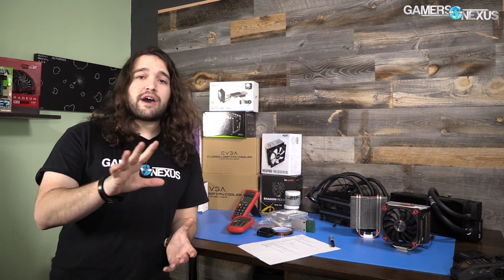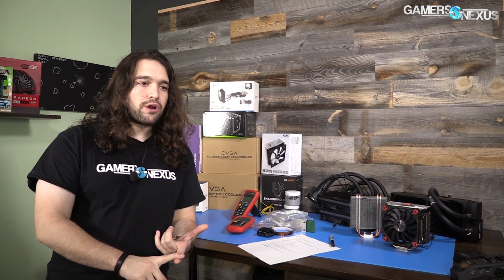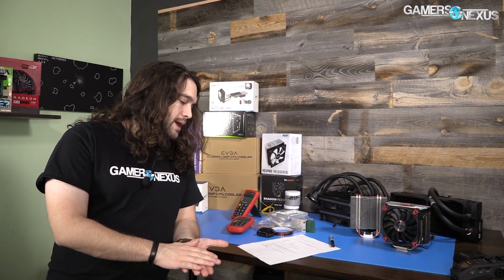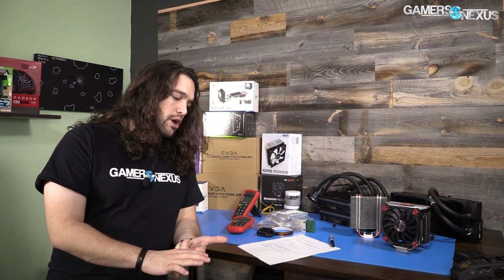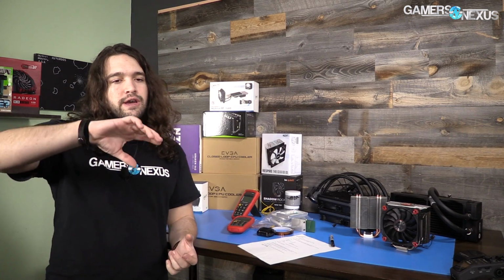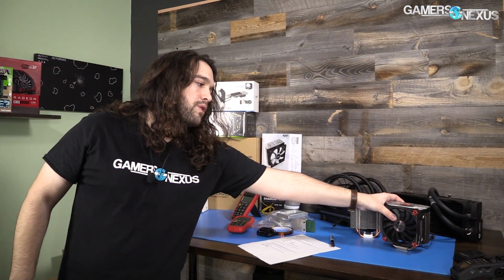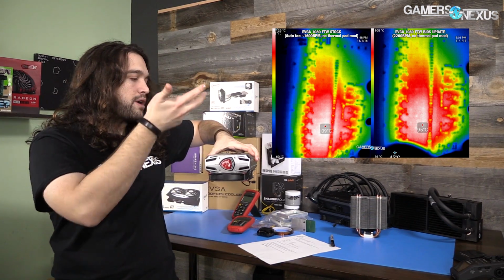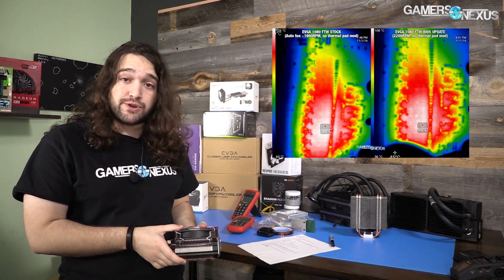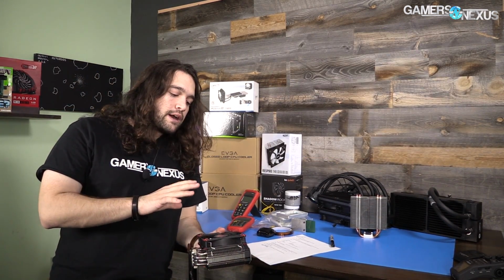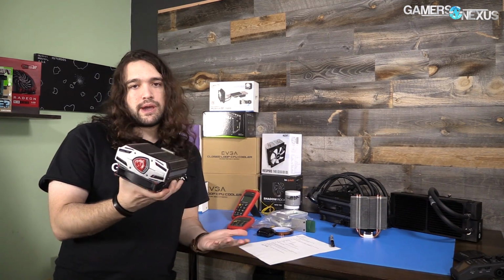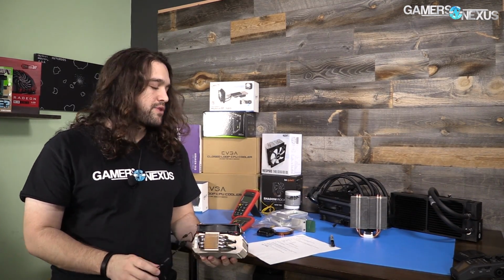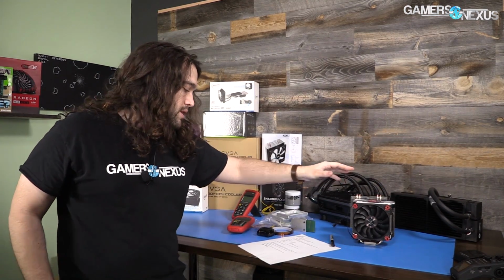Now, that's a valid test environment. That's a valid thing to look for, but it's got to be controlled and understood. So the example would be if you are radiating heat off the back of the card and you flip the cooler so that it is now oriented this way, it could be sucking hot air in through here, and that would actually increase your CPU temperatures because you're now pushing more heat through the cooler, and it's only got so much it can handle before it's kind of saturated. So that's something to look out for.